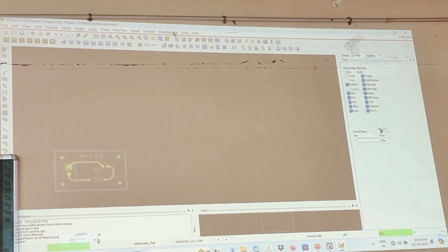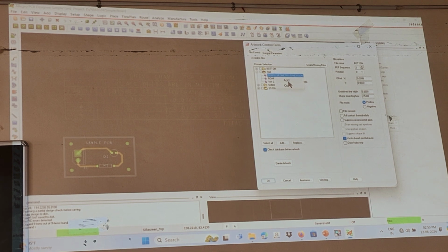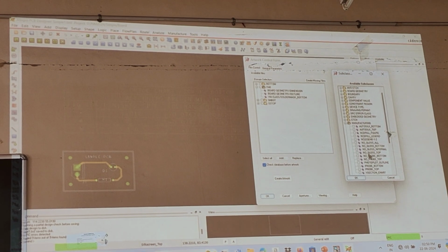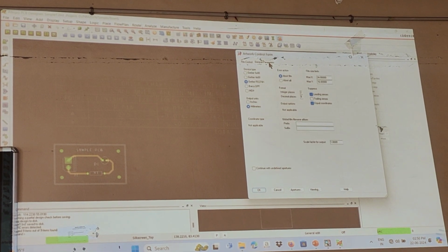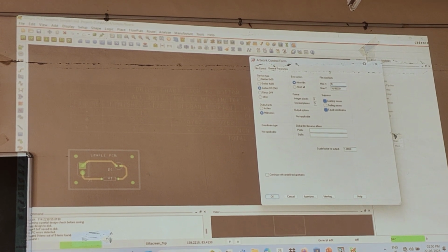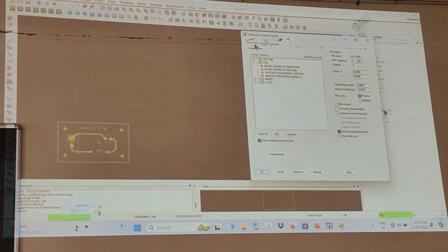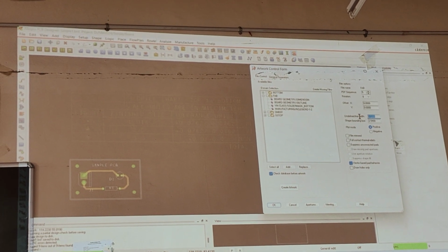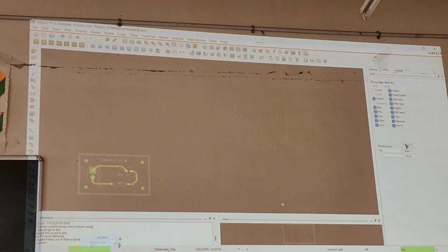So the legend has been created, and I am going to artwork, going to fab, and adding the legend layer of drill file. For that, manufacturing NC legend 1 of 2, then click OK, then the Gerber, maximum film size of 500 cross 500 mm, scale factor 1, film control. For the fab alone I am just giving undefined line width of 0.2 mm, and then I will just give OK.